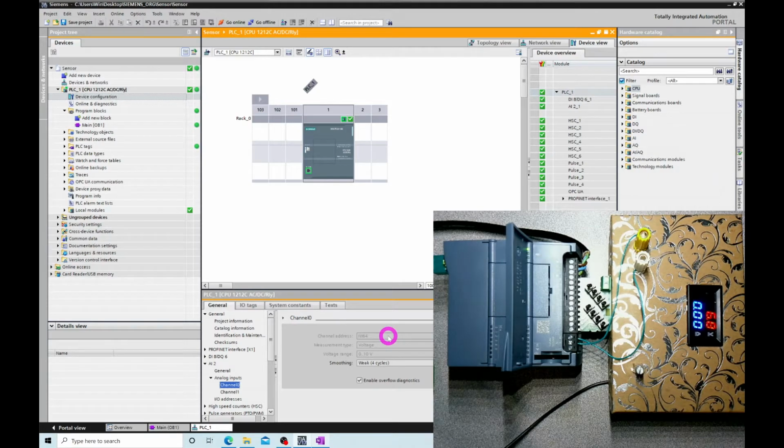If you watched our previous video on internal addressing, we mentioned that a word is 16 bits. Since this one is 64, the next one should be 66 to avoid address conflicts. If you didn't watch that video on internal addressing in PLC, please watch it, or click on the link at the top of the screen.